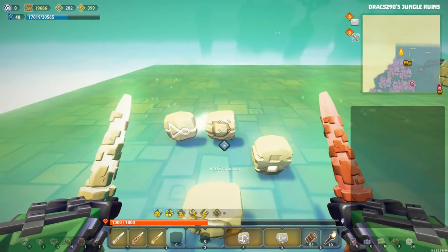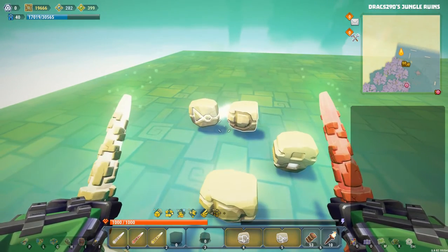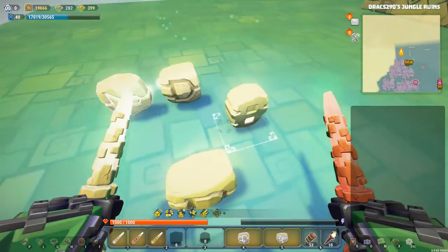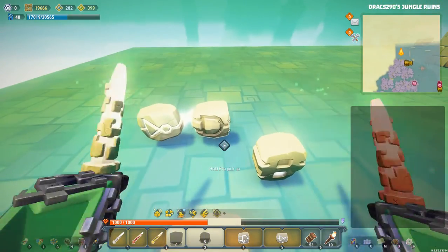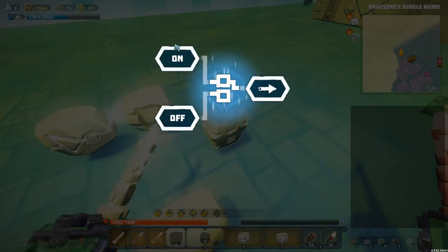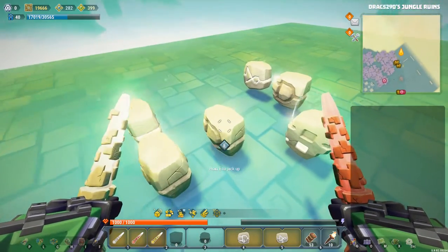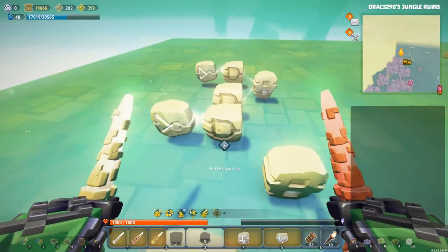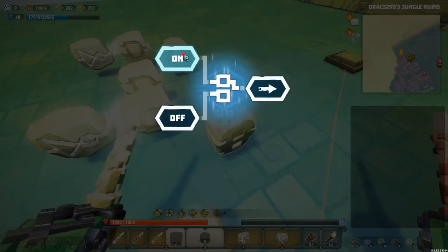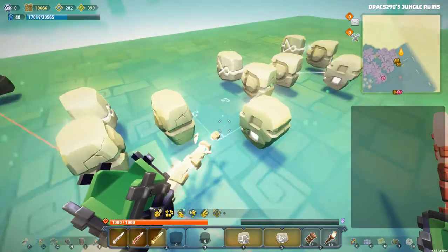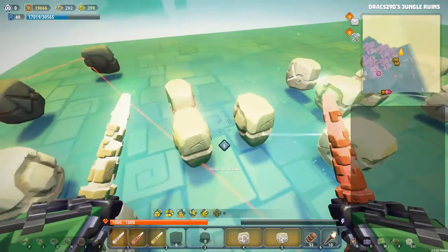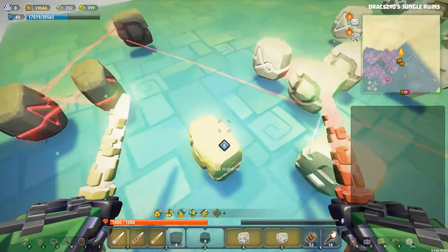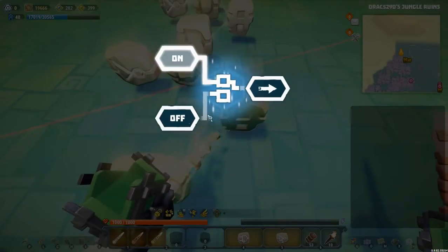And then we're going to go through and hook these up correctly. Now, this is once again just like a counter, so when the NOT gate is on, that means that the latch is off and we want to turn the latch on, so that's going to go into the on side. Then the other AND gate, the AND gate with nothing hooked up to it, goes to the off side, just like that. And we do this for all of these latches all the way down. So on and off. And once again, the one with the NOT gate goes to on. And the one with no NOT gate goes to off, just like this.